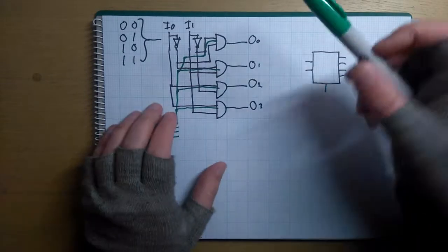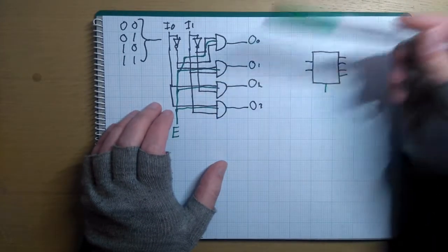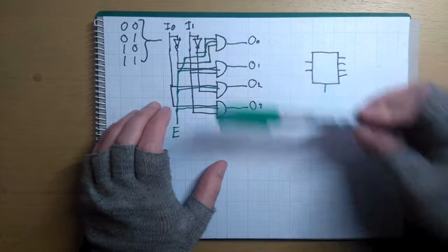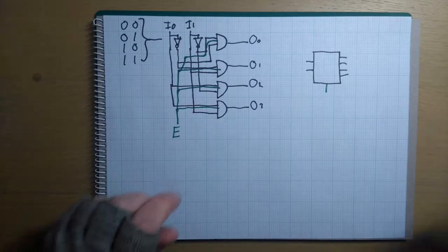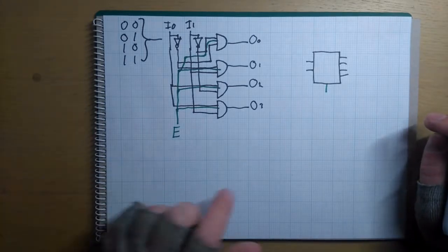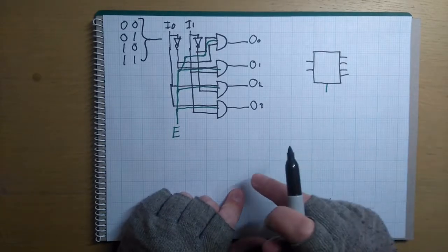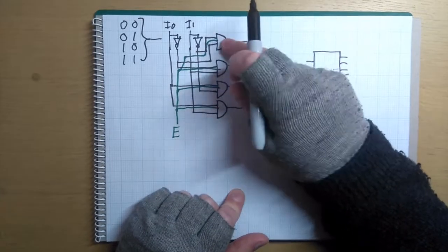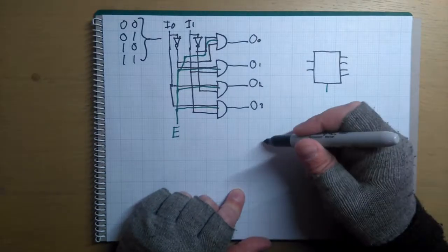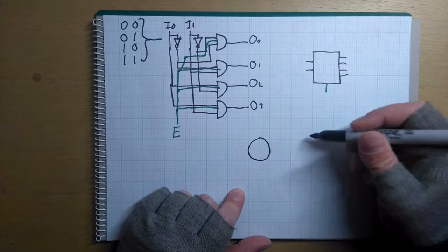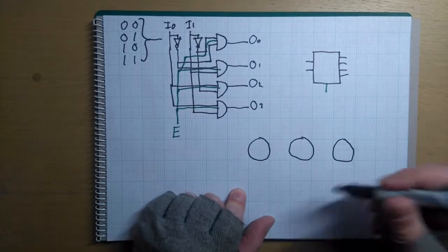So I'm not going to draw the entire schematic here. Right, in the last video, I already built the inverter, so you know how I'm going to build that. But the AND gate, how do you build an AND gate? So what it is actually is transistors. If you're doing enable, it's actually three transistors. You need a transistor for each input. So let's just do one here. So this is going to be one AND gate.